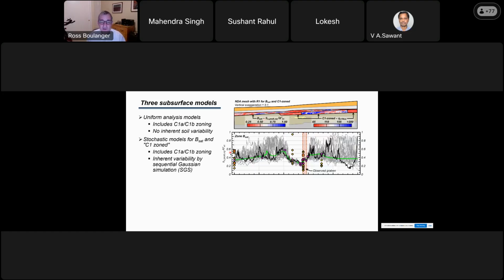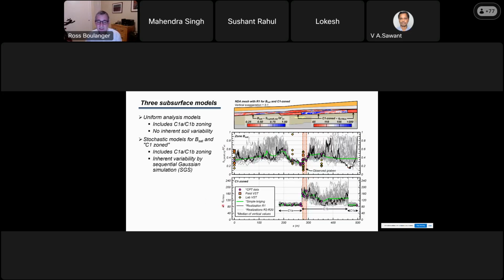And then this is showing the variability in the undrained strength of clay along the alignment of the road. This is the variability in the predicted cone tip resistance. The gray lines are the realizations. The black line is one realization to flag it out for you. The purple dots are from the CPT data averaged in columns. You see very little variability in this location because that's where they had a lot of CPTs. And if you have a lot of CPTs, you know the properties and you don't have a lot of uncertainty. Up here, there's a lot of variability because there aren't any CPTs. And when you don't have CPTs, you have more uncertainty in properties.